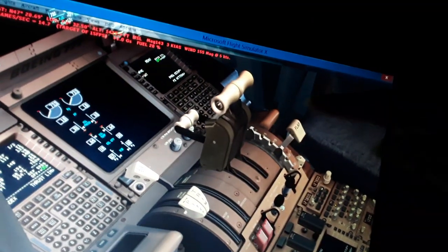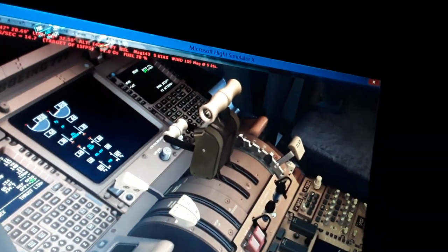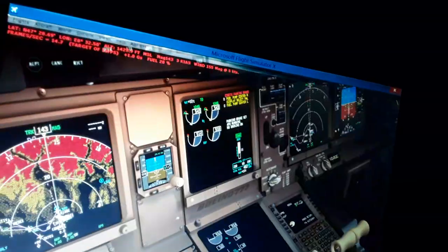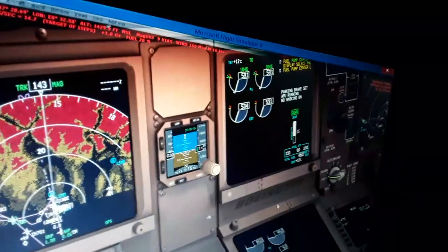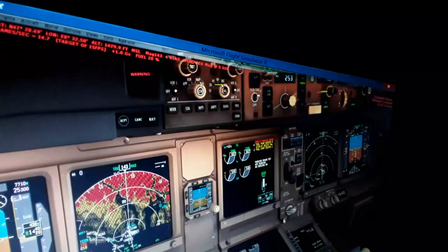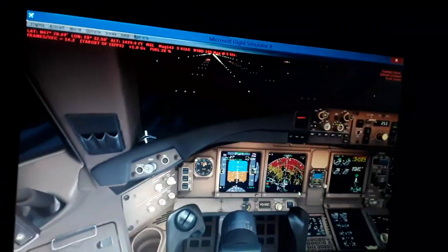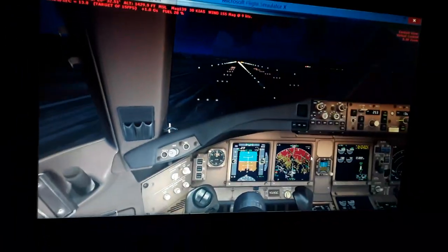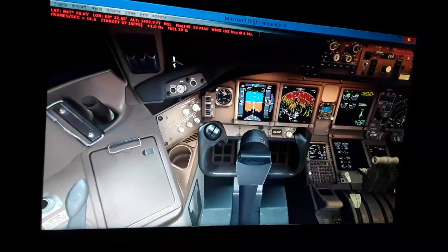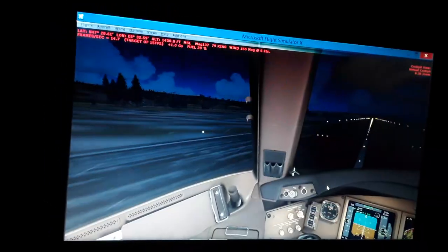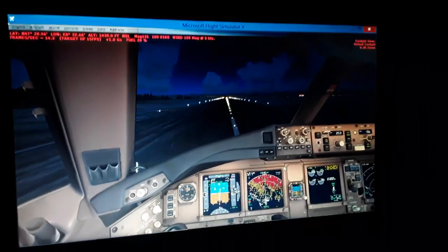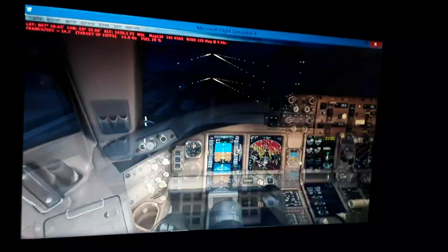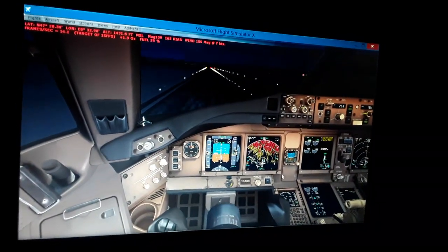Advance the thrust levers, the flaps are set for takeoff, and the fin stabilizer. Over here we have the thrust set. Advance the thrust levers moving forward, disarm the parking brakes and go, and align with the rudder pedals. So here we go. We have 100 knots. V1, rotate, V2, align with the rudder pedals also.